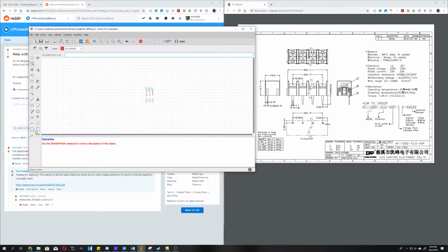Yeah, that's fine. And you could maybe make it something fancy. I don't know. Draw a rectangle around it. Sure, why not? You can draw whatever you want. The key is you want to make sure that the origin is somewhere where you know it is. That's that kind of faint light cross there. One useful thing when you're working in these, if you select everything using the selection tool, then you go to the move. If you control right click, that applies everything you do to a group. So that's a really useful control.